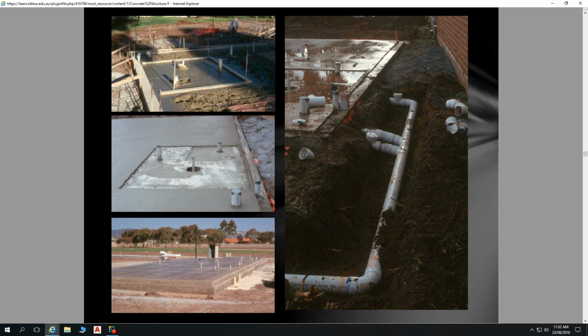So in case a toilet is blocked or the system's broken, it's just like pouring water in there, but that water goes down that floor trap and not out into your lounge room or anywhere else in the building. So you create a set down in the bathroom. You've got slope relationships as set out by the National Construction Code as to what minimum slope you need on your bathroom floor, and then you calculate your set down accordingly. They've also got a separate set down for the shower here as well.